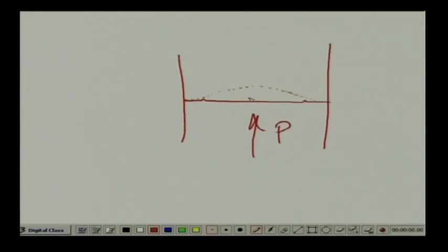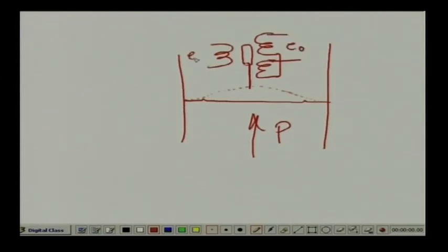Now, the interesting thing is that the linearity of the diaphragm depends on how much the displacement is. The less the displacement, the better the linearity of pressure versus displacement. So, if I now connect a core of an LVDT like this, with primary and secondary and an output voltage, I have an excitation E x.